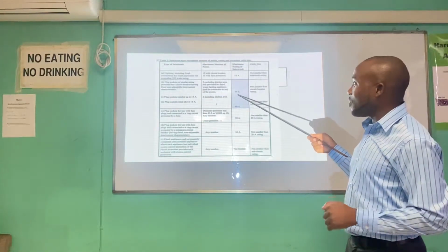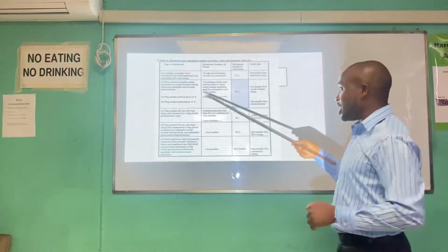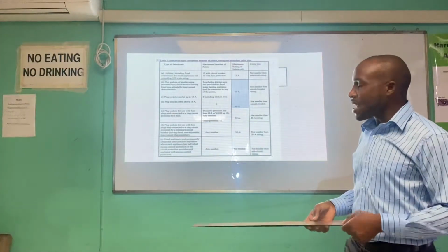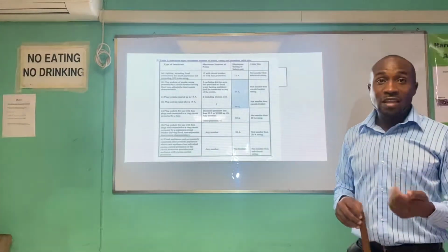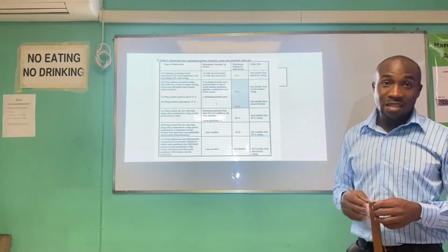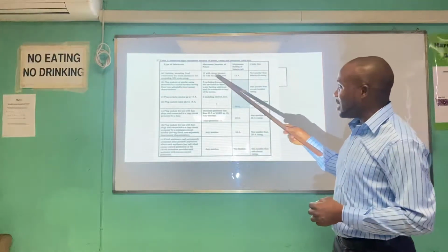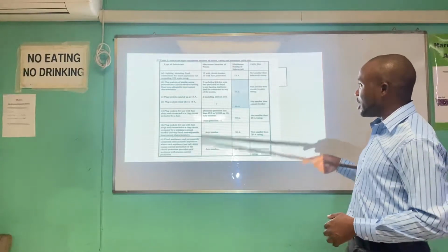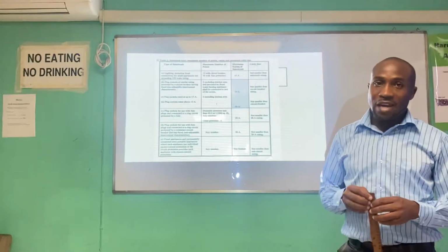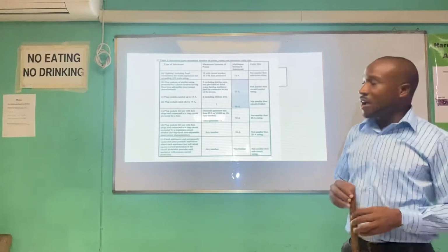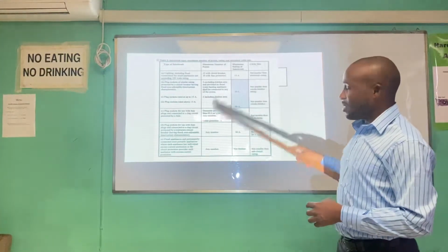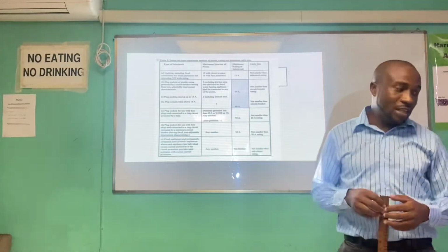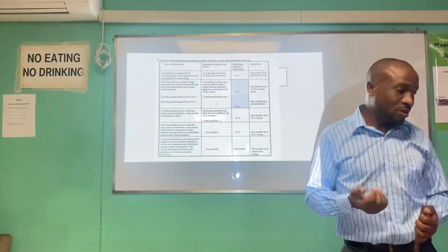And we're not talking about specialized items as yet. Kitchen area is not included. AC breakers are not included also as yet. So by designing and determining exactly how many light circuits you need and how many plug circuits you need, you can easily have an idea of the number of breakers that you're going to need for your main panel. So it's still a part of the design. We're still looking at layouts and so on.